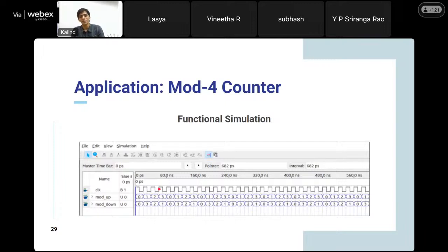It cannot be directly translated because what you are writing in the case of a microcontroller is C code or Python code, for example, right? It cannot be directly translated onto FPGA because in the case of C or Python, you are writing software, as I told you, correct? You are defining some variables, you are defining some functions, and then you are asking what that particular function should do. But in the case of FPGA, the code that you saw in the case of Verilog or VHDL, you are actually writing the code to realize the hardware directly onto the FPGA.